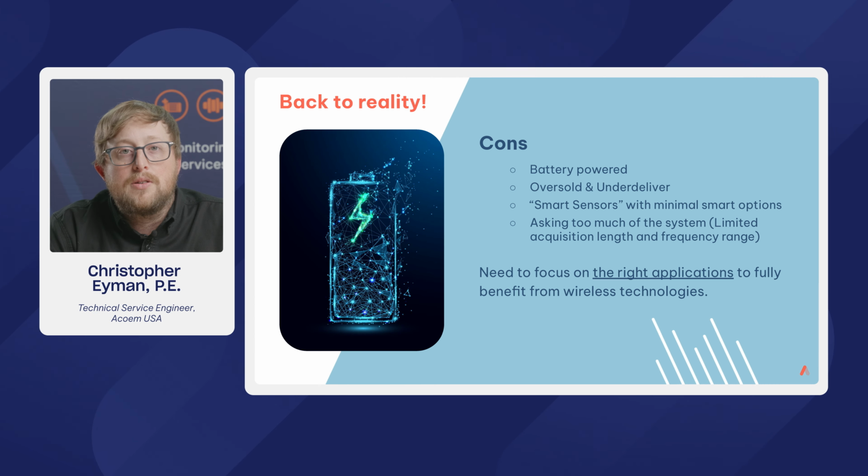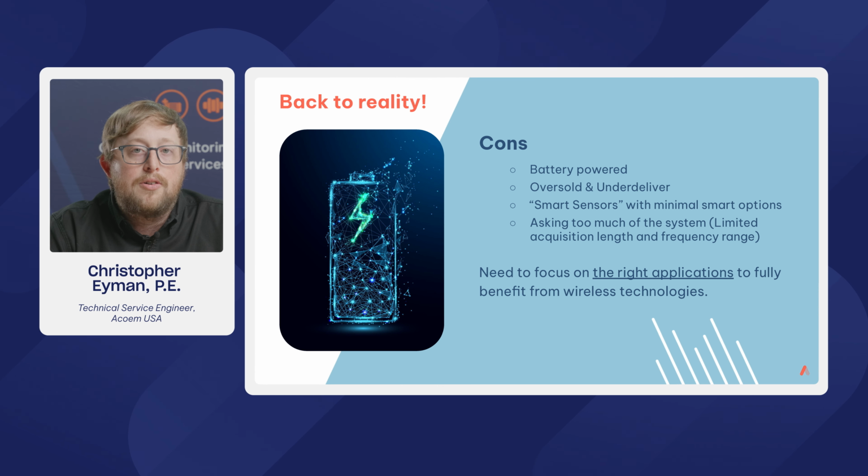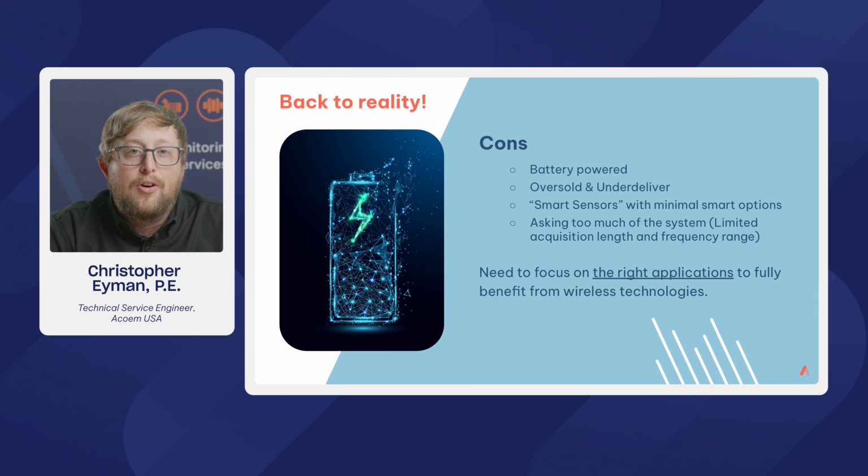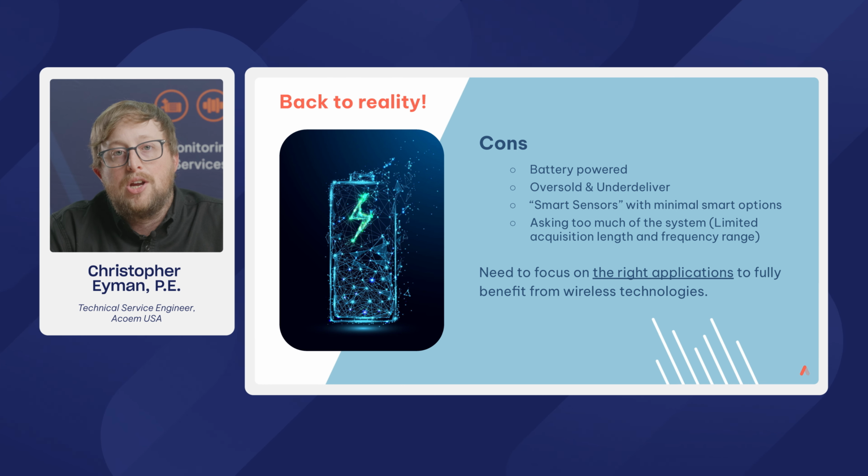I think a lot of these systems are also oversold and under-deliver. They're oversold that they can solve all your problems, but really they don't work in all applications. The sensors are also sold as smart sensors with minimal smart options. Most of these sensors turn on, collect data at the interval that you've set them to, and then they go back to sleep to preserve battery. They won't trigger based on alarm, and they won't wake up if something happens, like a condition or state change.